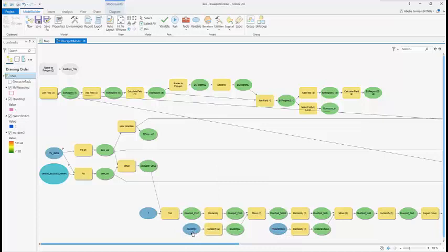And again we will use the raster buildings and convert them into polygon because we would like to add these buildings on top of our final blue spot region to see how many buildings will be flooded or will be intersected with this flood area, and then we can quantify the number of buildings that will be at risk and at high risk, and the ones that will not be at risk. For that we need this raster to polygon tool.